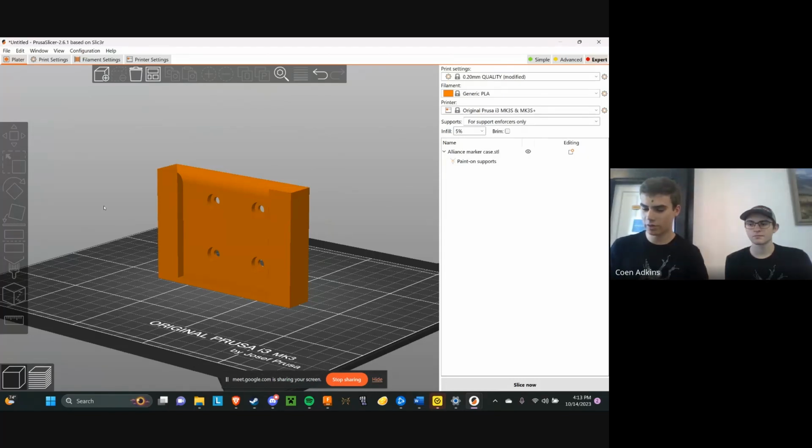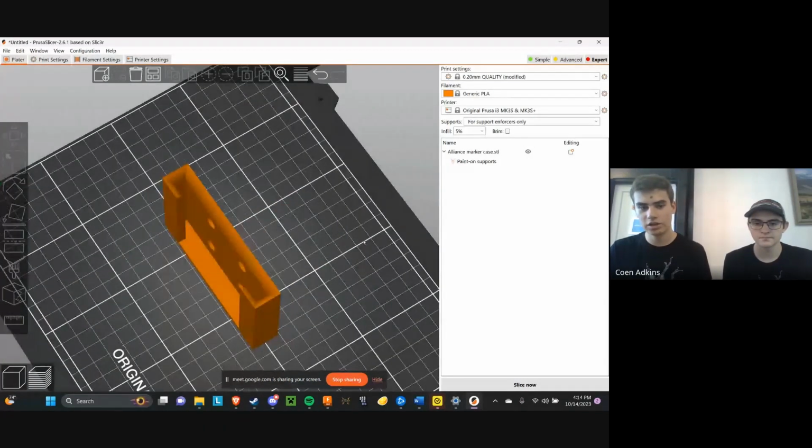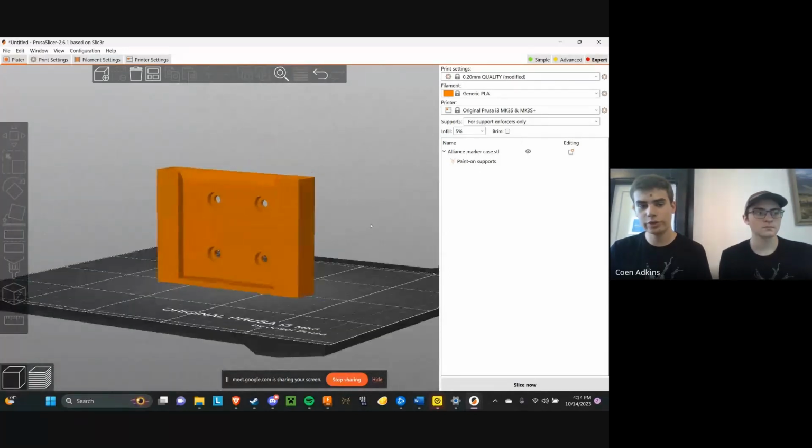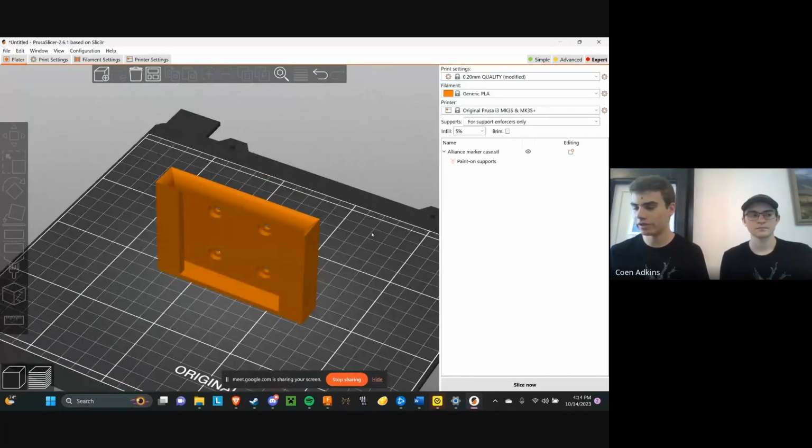So like last year, there's one component on our output, it was the wrist, and it basically just held a servo, but that servo had a lot of weight on it. So when we were designing it, we made sure that certain parts where there was a lot of force were thick enough to support that weight, and then we made sure the orientation was good enough so that there wasn't any force on the layers, and through iterations, we've found how to design that part perfectly.